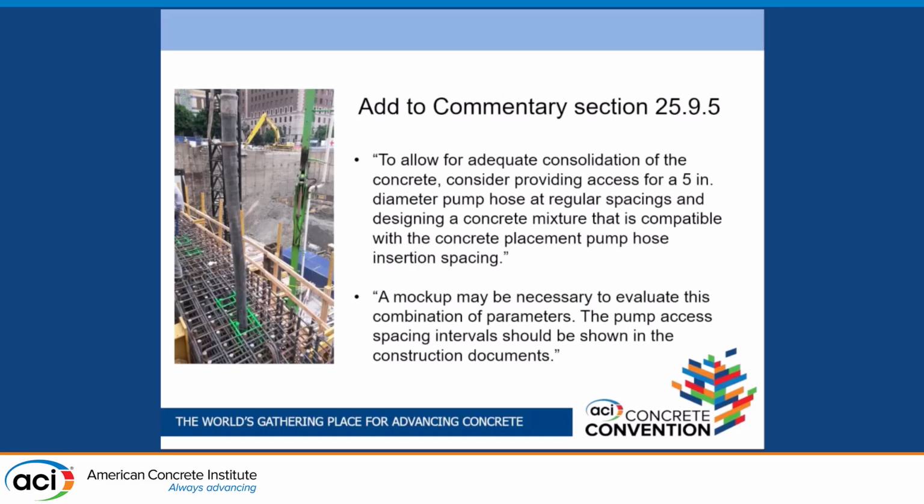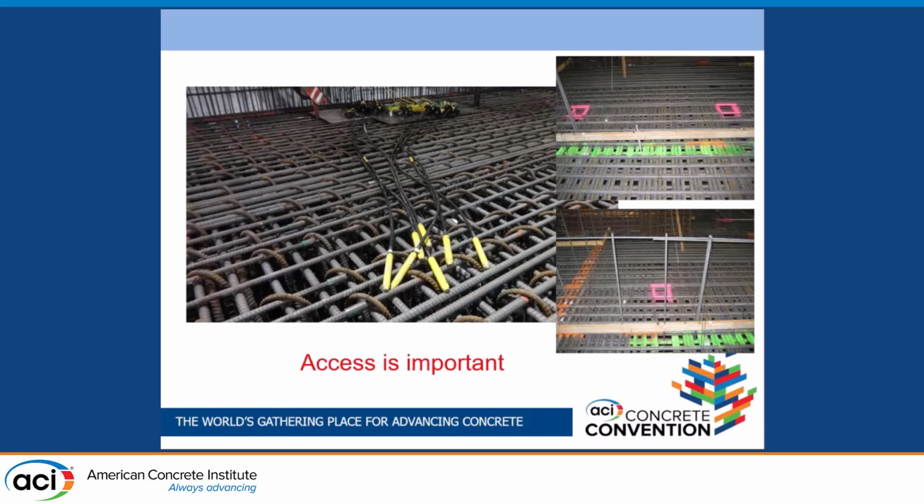So as we're looking at that, we obviously recommend providing better access to consolidate concrete and to get the concrete closer to the placement location. So making sure we add areas where you can actually put the pump and the concrete can get to the right place. Access is important.